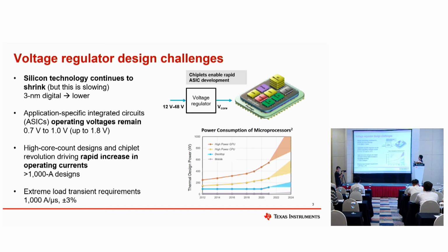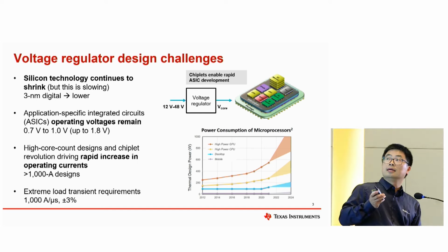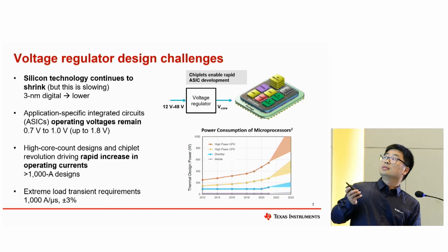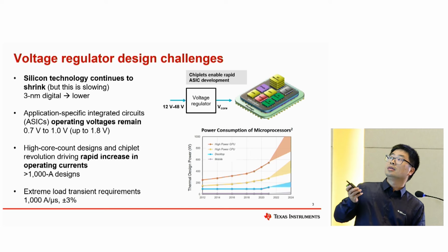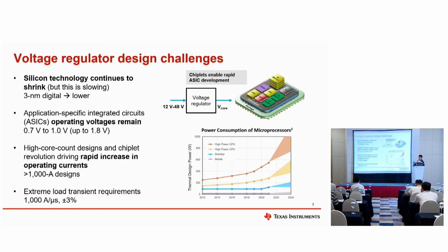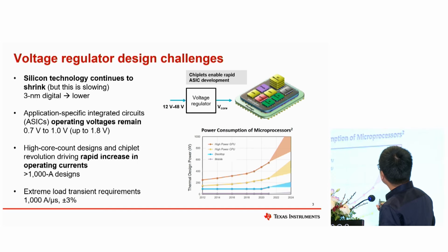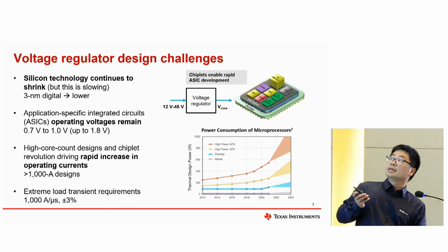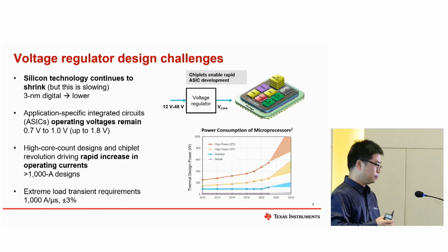This is true, but most recently there is a new architecture called the chiplet. The chiplet architecture means dividing the different function parts, like the CPU, GPU, and ASICs, into different dies and co-packaging them in a big package. So the designer can output a new power IC as quickly as possible.